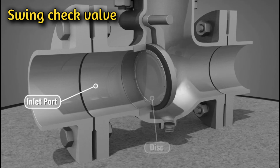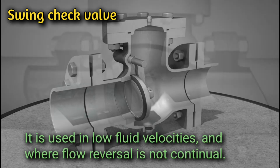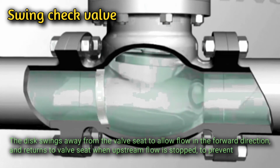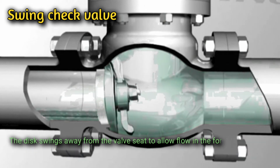Swing check valve. A basic swing check valve consists of a valve body, a bonnet, and a disc that is connected to a hinge. It is used in low fluid velocities and where flow reversal is not continual. The disc swings away from the valve seat to allow flow in the forward direction, and returns to the valve seat when upstream flow is stopped, to prevent backflow.